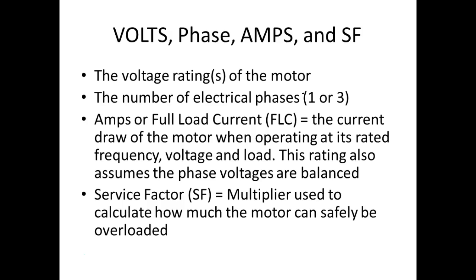Everybody should understand this. Phase, amps, and service factor: the voltage rating of the motor, the number of electrical phases, 1 or 3. Amps, or full load current, is the current the motor draws when running at its rated frequency and rated voltage under its rated load. This rating also assumes the phase voltages are balanced. So if you have a 3-phase motor at 240 volts, then all 3 phases had better be 240 volts. We assume that all the phases are balanced.